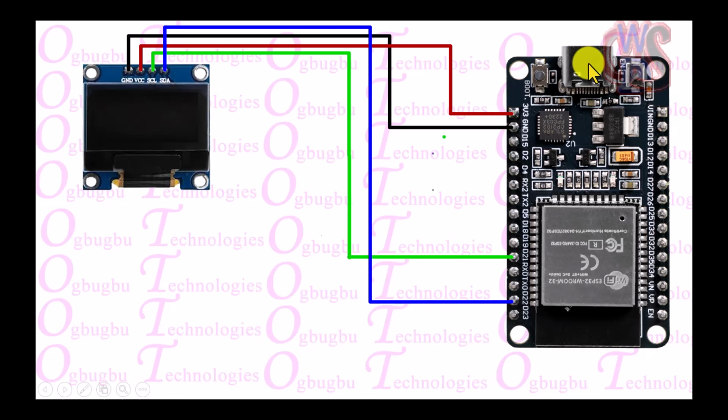because the moment you pass in 5 volts into this dev board, 5 volts will go straight to this OLED display, and there is a converter behind it, a voltage regulator, which is meant to bring the voltage from 5 volts, or whatever voltage you are passing to it, down to 3.3, but most times it just ends up damaging the OLED display. You discard this entire OLED display not knowing what is bad in it. It's just a few cents, but you need technical know-how to even know what that is in the first place.